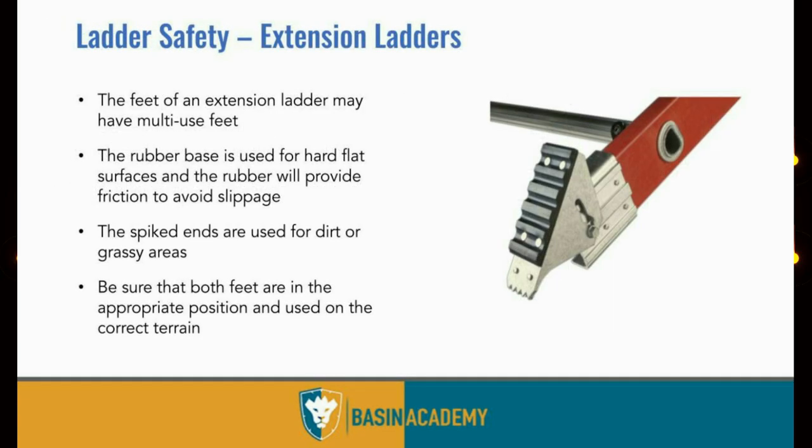The feet of an extension ladder may have multi-use feet. The rubber base is used for hard flat surfaces, and the rubber will provide friction to avoid slippage. The spiked ends are used for dirt or grassy areas. Be sure both feet are in the appropriate position and used on the correct terrain.